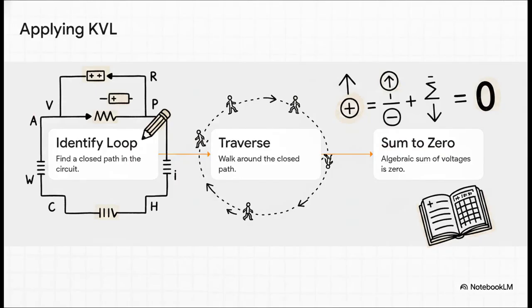So if you're ever stressed out trying to solve a circuit problem, just take a breath and break KVL down into 3 calm, simple steps. First, trace a closed circle on the page. Second, mentally walk around that circle and note every component you pass. Third, add up the energy sources, subtract the energy drops, and set the whole thing to 0. Boom! It's not intimidating math, it's just accounting.